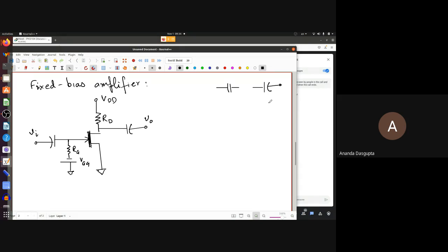That is, when you are setting this up for DC, you have to make sure that the polarity is just right, otherwise the capacitor simply will not work. And here, the straight and curved line simply means the straight line should be connected to the positive side of the DC, and the curved one should go to the negative side.